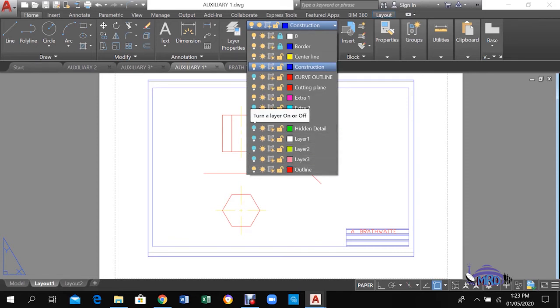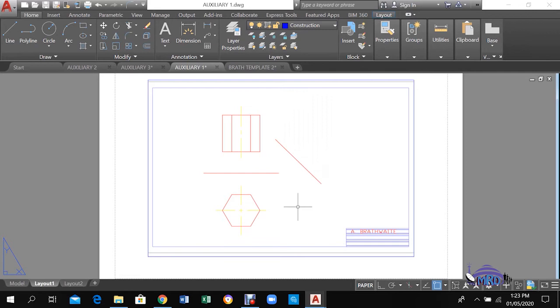So for this construction then, you are given a hexagonal prism. Remember, a prism is a column. So you have the plan, which will show you a hexagonal shape, and then you would have the faces as represented on this front view here. Now, the XY line is always in, so you can see that XY line in, because a lot of what we do is reference to the XY line, so you have to bear that in mind as well.